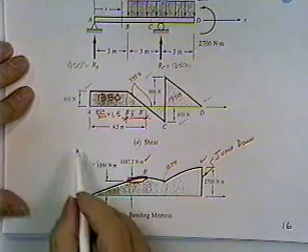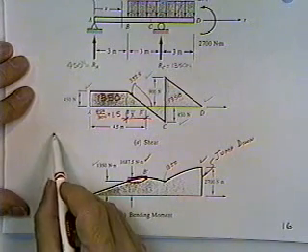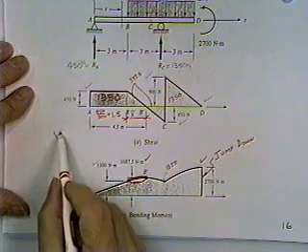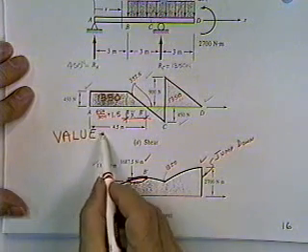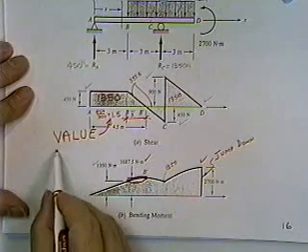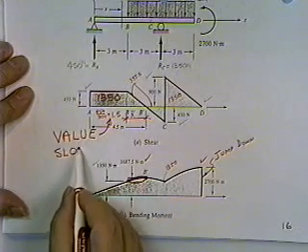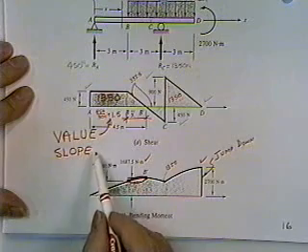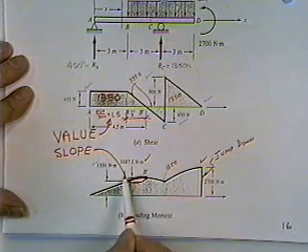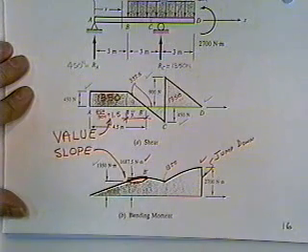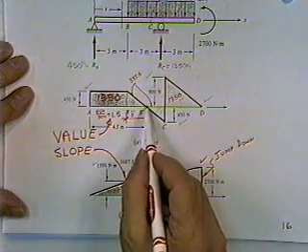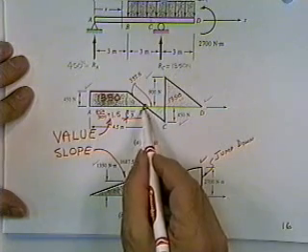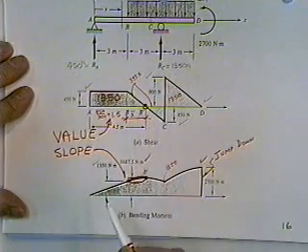You do that by, again, the mathematician tells us that the value on any curve up here predicts the slope exactly underneath that point down here. The value on an upper curve gives you the corresponding slope on the bottom curve. Now, if you'll look at point B prime on the shear diagram, the value is 0.